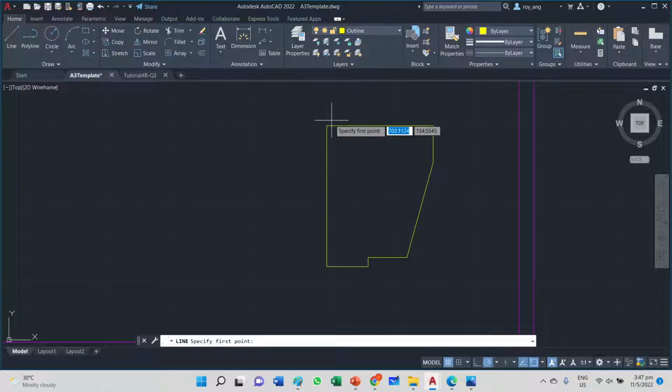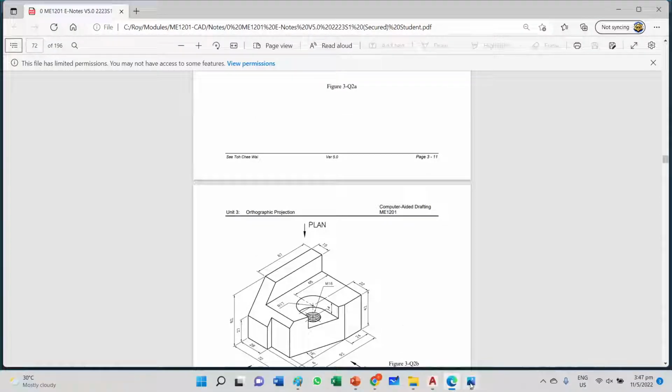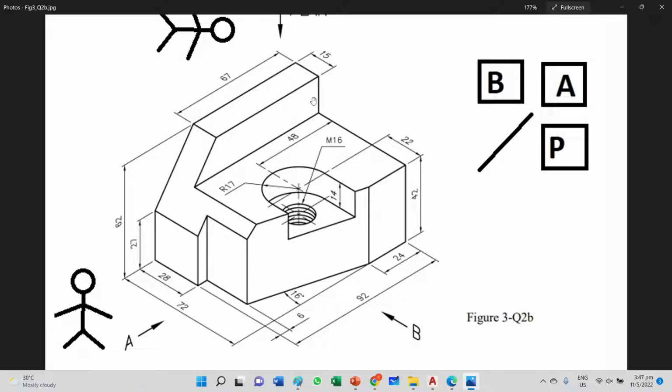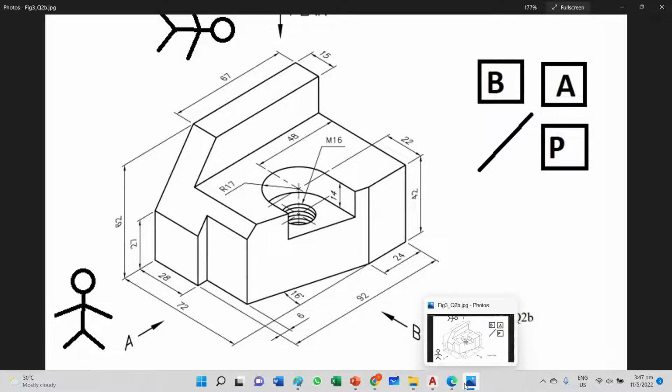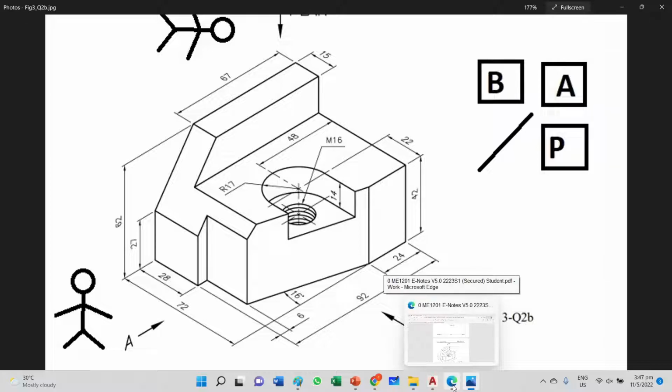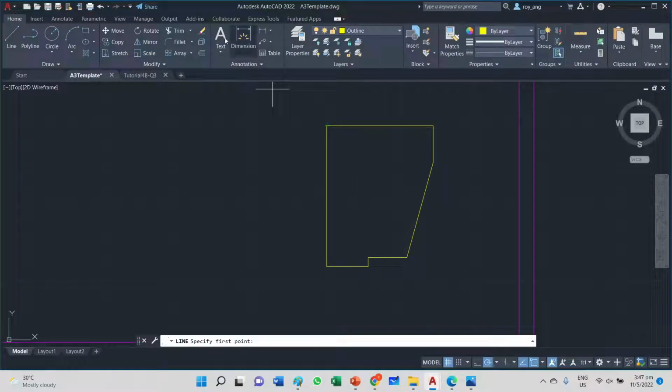Okay, and I'm going to draw the top segment here. And there is a center line that I'll draw for my countersunk hole. I'm going to draw this part of the segment because the dimensions are given. I know there's an offset of 15 millimeters, and it goes in by 67. And it ends here. From the top is 67. And the next thing that we want to address, the end view pretty much looks like that. There is not much features.